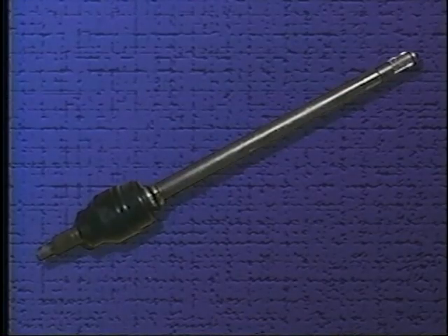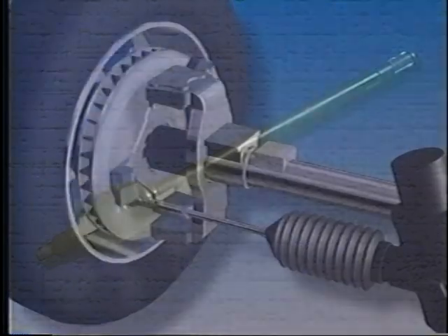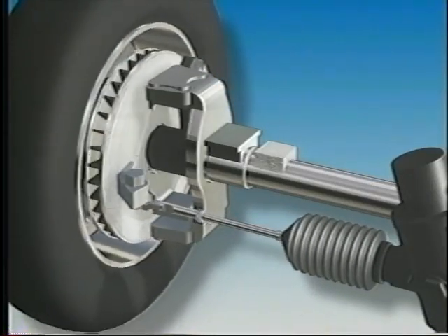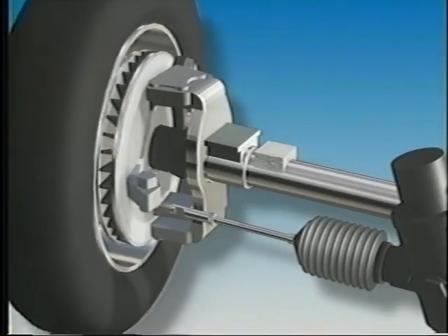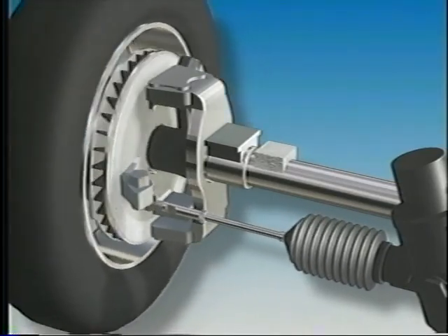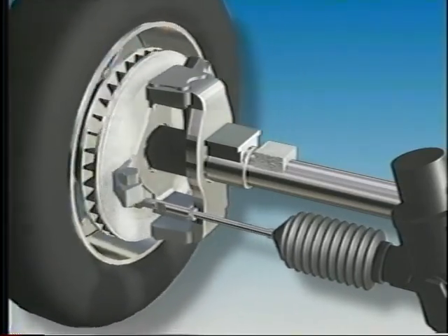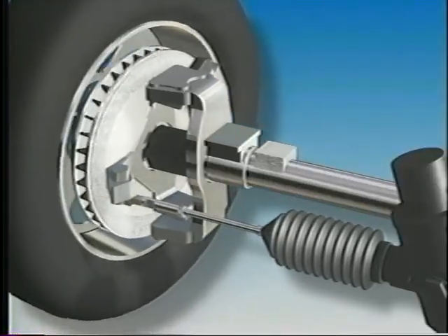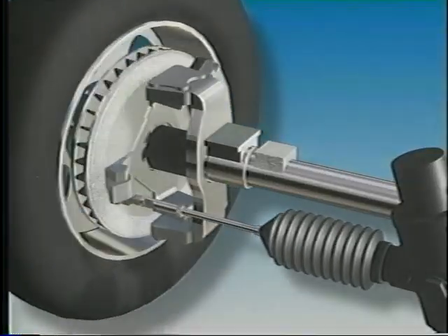Quarter shaft operation parallels what we've seen on other axle shafts that are a constant velocity or CV joint. The rear axle quarter shaft knuckle joints are able to move independent of one another. This allows for individual quarter shaft movement, though due to mechanical constraint, only normal axle rotation and steer of the wheels at CV joint is allowed. On a practical level, there is no camber or caster adjustment. The only adjustment is for toe.